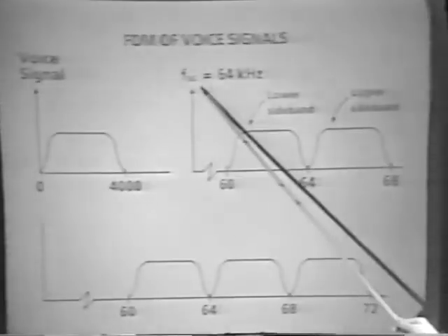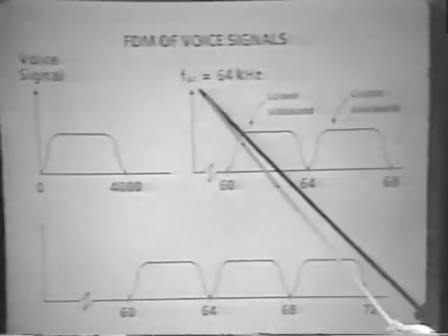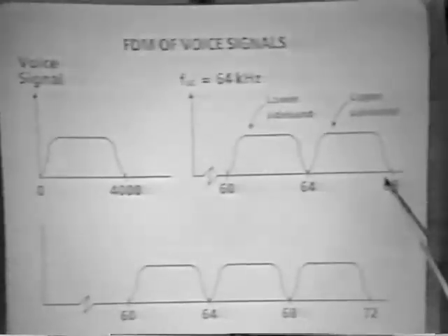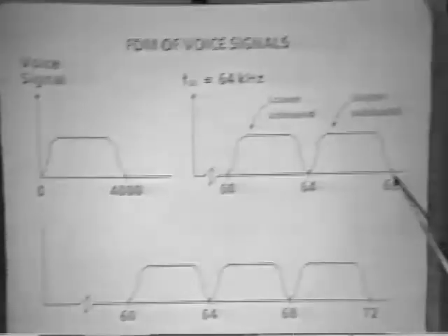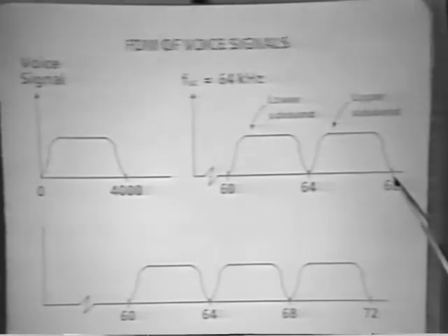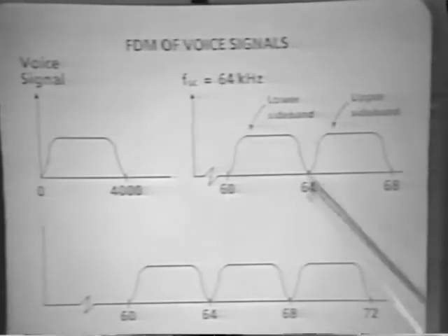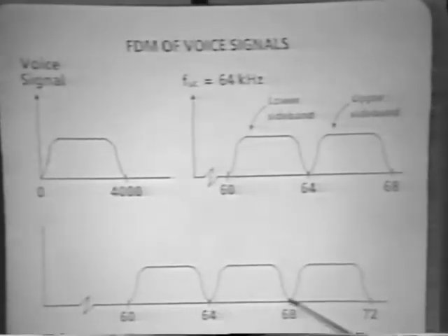Now, if we were to modulate that signal, this is an example of analog data being modulated onto an analog signal, we would end up with an 8 kilohertz signal centered at the carrier frequency and having 2 sidebands. What's typically done with voice signals is to take just the upper sideband, to delete the carrier and the lower sideband, and to send out the data in this fashion, so that multiple signals from various sources can be modulated by particular carriers and share the same line.